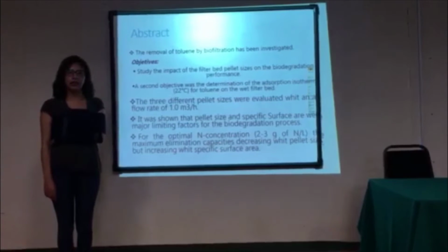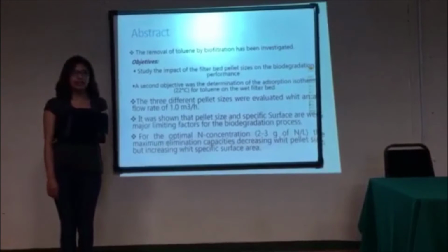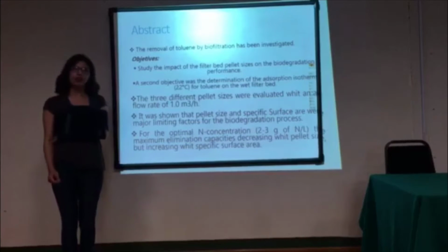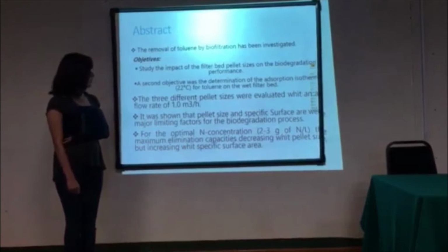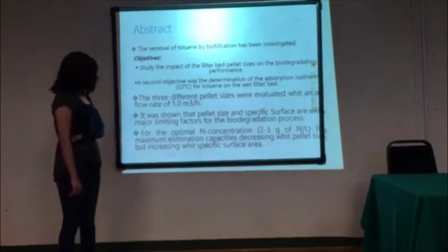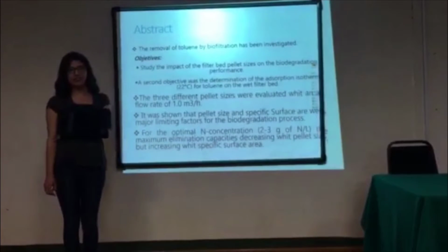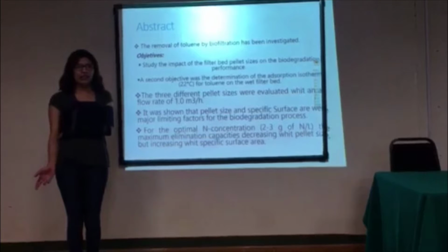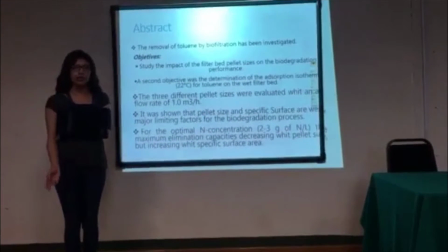Another point in the abstract was that 3 different pellet sizes were evaluated with an airflow rate of 1 cubic meter per hour. And it was shown that the pellet size and the specific surface area were limiting factors for the biodegradation process.